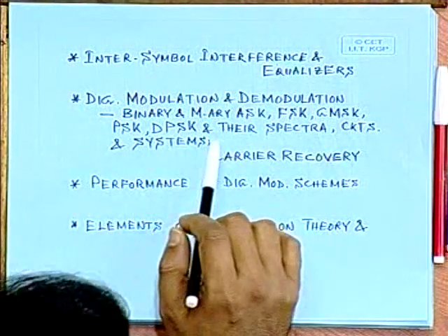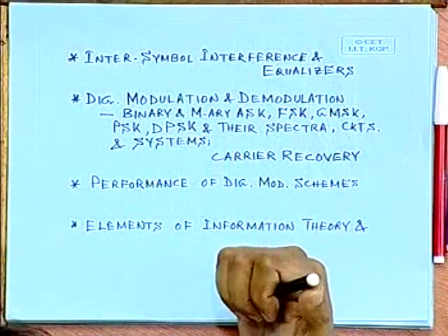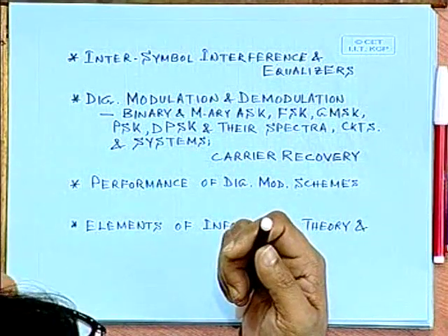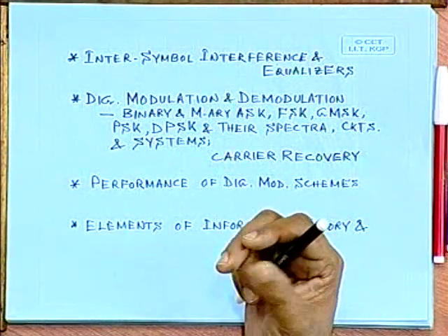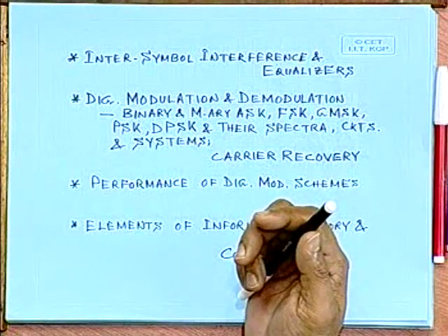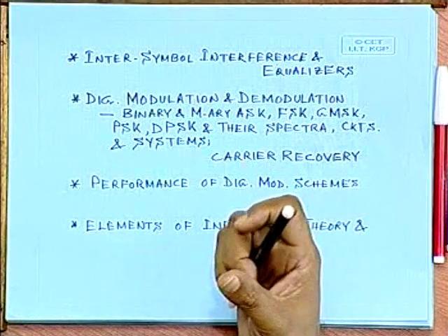Digital modulation and demodulation, as I said, is a very important issue, because that is how we translate the basic signal represented digitally from one frequency band, which I can now call the baseband or the basic bandwidth of the signal, to a rather high frequency band, which may be called the intermediate frequency, IF, or even an actual transmission bandwidth, which is called RF or radio frequency bandwidth.